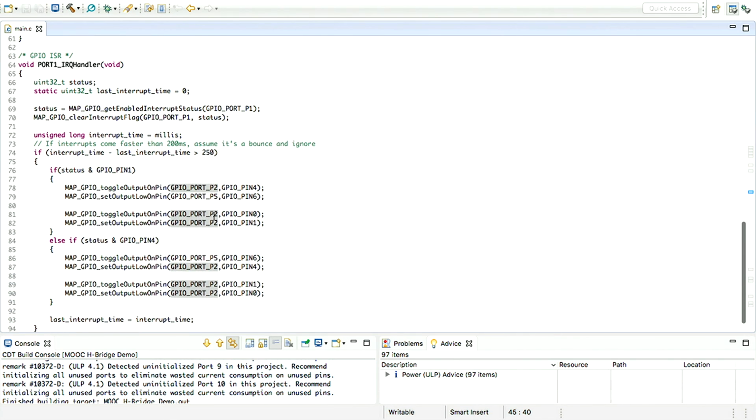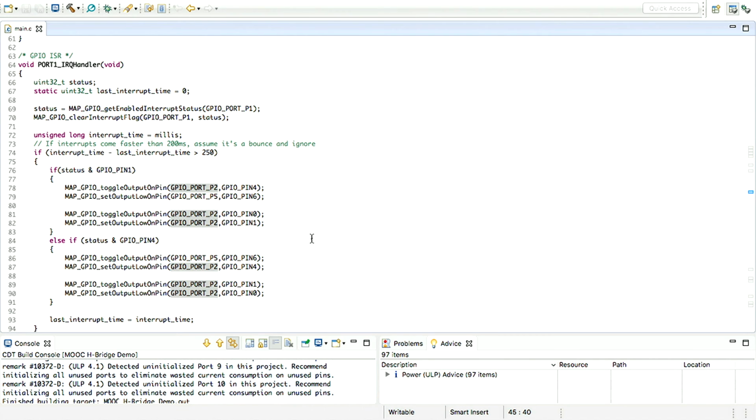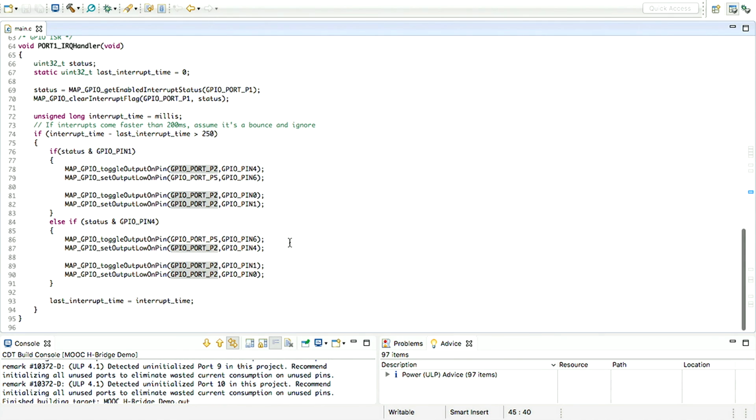Going down to the bottom of our program here, this is what we call an interrupt handler. And this function is going to get executed whenever we push one of the buttons. And so what happens here is when we push one of the buttons, we will toggle the digital logic signal on one of our pins. So on either pin 2.4 or 5.6, we'll toggle those pins to turn the motor on and then turn the motor off when we press it again.